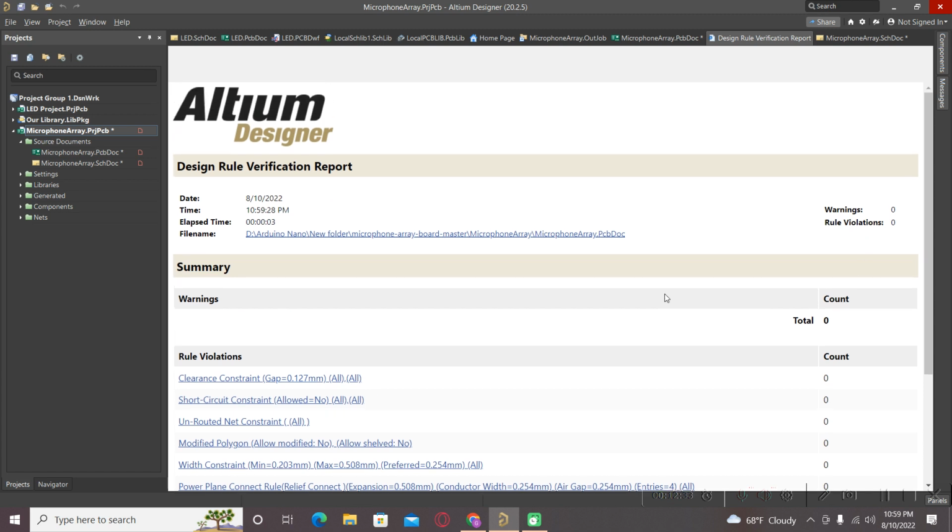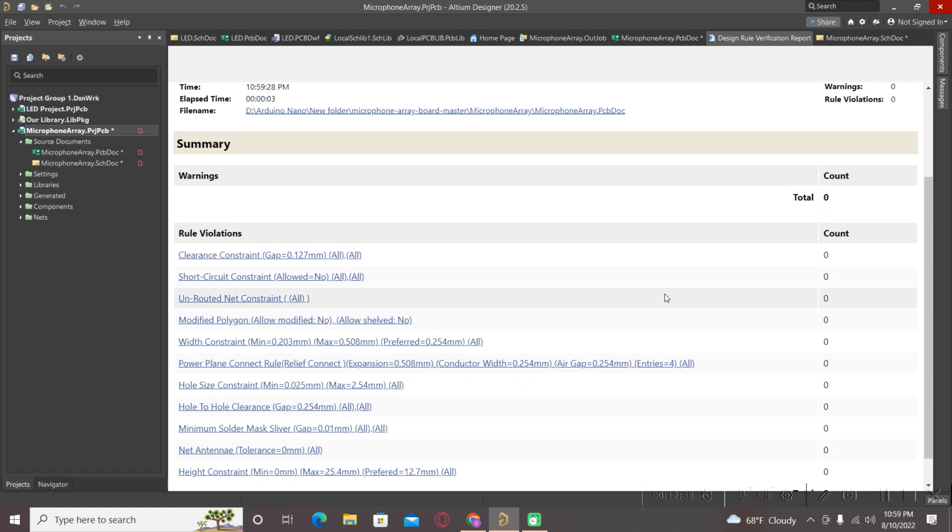Only in this special case we put the clearance almost zero, because sometimes the violations are not so critical, but please be aware and always take care regarding the other violations, because some of them are very important, and turning them off is not always the best solution.